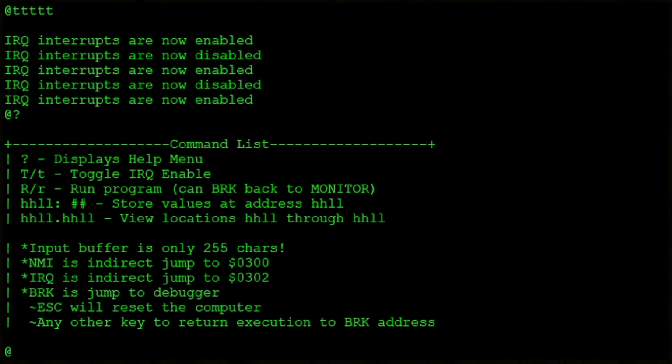The next command on the list is the store command. I'm going to skip over the run command, at least for now. The lowest 8K of the system is RAM, which means from address 0000 through 1FFF is all RAM. And the system only uses the zero page and page 1 and page 2 of the memory. So that means past 2FF hex, the rest of the system is free, at least RAM-wise. So at address 300, that's RAM that's not being used.